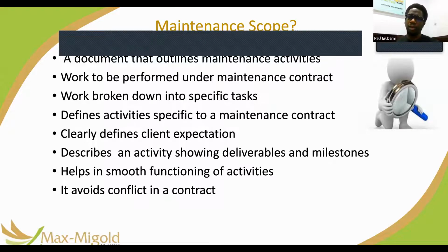Then they check the oil level. If the level is okay, then they use their hand to feel the oil viscosity. If it is too low, then they will take out the oil and put new oil. But if it feels a bit okay, what they will do is check if it is reduced in quantity. If it's reduced in quantity, they just do a little top up. And this was going on and on for months, running into a year.